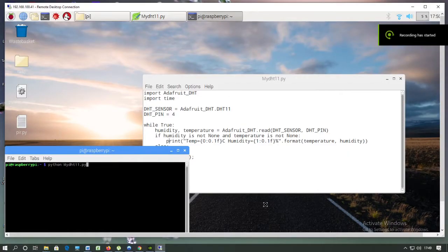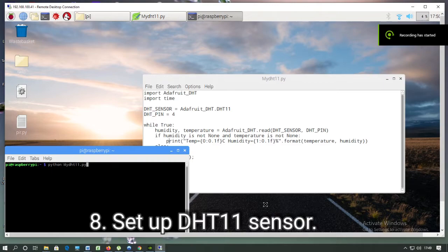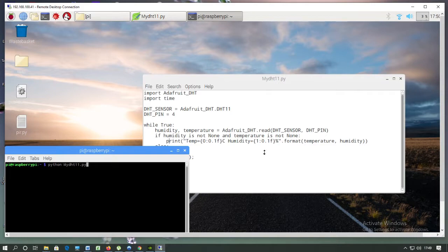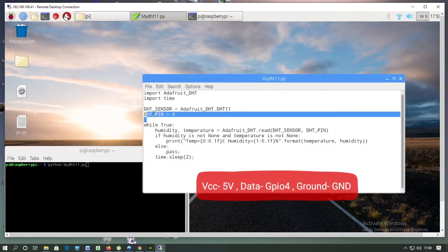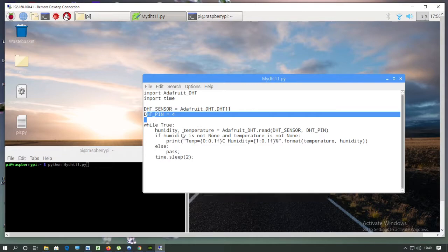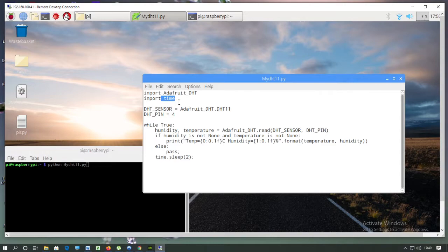Now proceeding to the first sensor, the DHT11 sensor. The DHT pins are connected to the GPIO4 where data is received, and it is powered by a 5V pin from the Pi to the sensor. In the code, the time library is imported to handle the timed operations where checks are done every 2 seconds.